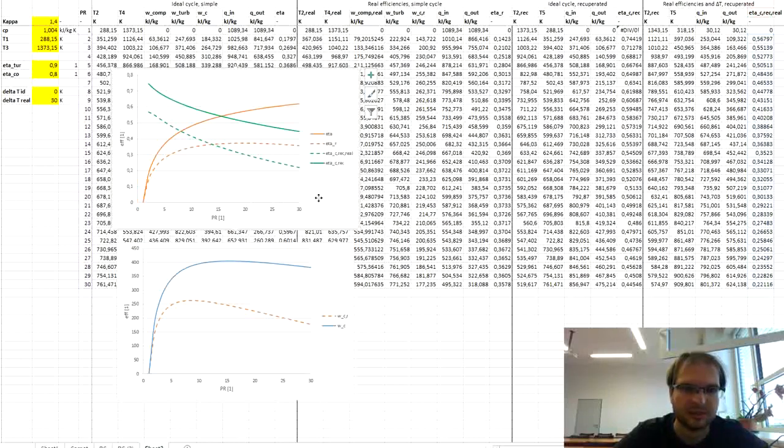So you could say that, well, the recuperated cycle seems as the best option. Let's build only these and receive very high efficiency of the system. The problem is that at the low pressure ratios, the work of the cycle is rather low, so it would not be feasible for building large systems. And at the same time, we also neglected important thing, which are the pressure drops.